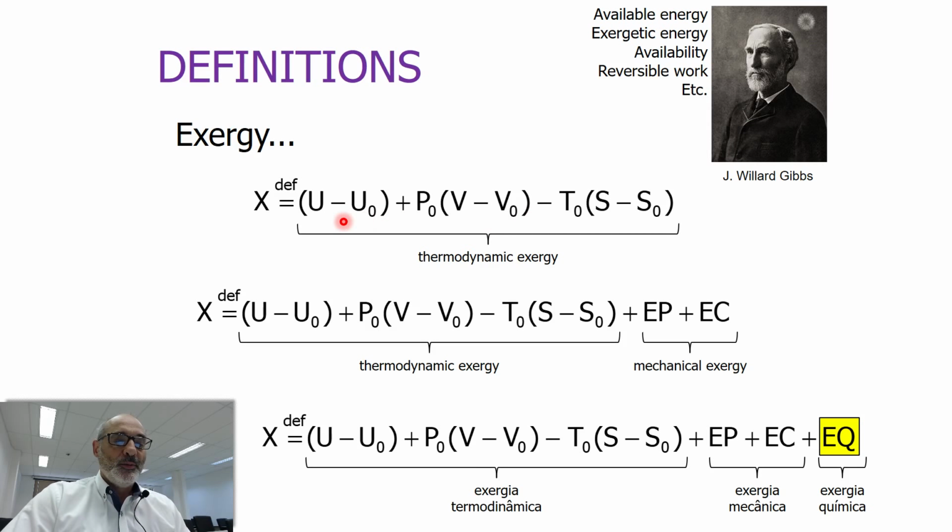So an important aspect of exergy is that it also considers the properties of the environment. If you're analyzing, for instance, a power plant to be built, I don't know, on the equator, it will behave very differently if it's built on the South Pole, and this can be taken into account in a very straightforward manner by using exergy.